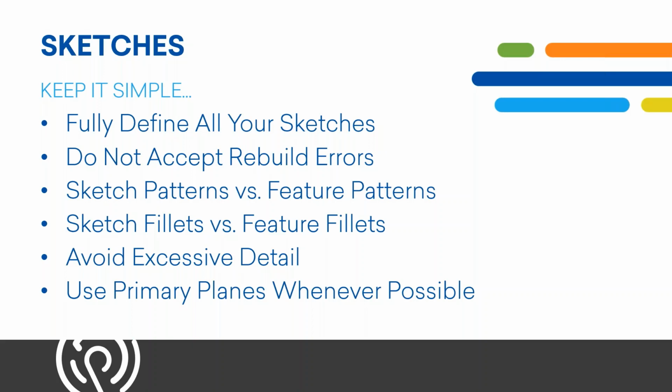All right, so for some of the other tips of working with sketches versus working with features, this comes up a lot with engineering and design intent. Sometimes it's down to preference. SOLIDWORKS allows you to either work with a 2D sketch entity like a fillet, or a linear pattern or a circular pattern, or you could work with it as a 3D entity as something of a feature. For this example using large assemblies, we're going to recommend features.